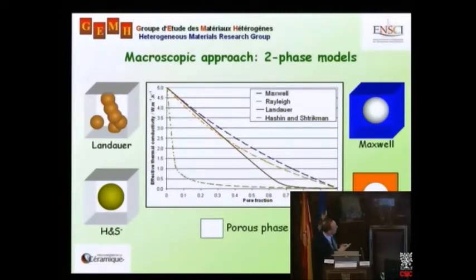Again, we see a decrease in thermal conductivity as we increase the pore volume fraction, but it is in fact steeper. And this point here, about 15%, gives you the transition from closed porosity to open porosity. Okay? You can see how Maxwell's predictions and Landauer's predictions separate.